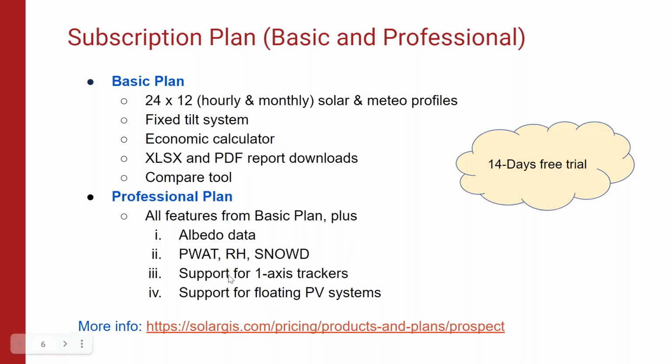the albedo data, which is very important, because as you know, the albedo can be used for bifacial gain estimation. And you also have additional parameters such as the precipitable water, the relative humidity, and the snow data. These are very important pieces of information that can have an impact on the electrical production. And you can also do the simulation with one-axis tracker or just a floating PV.